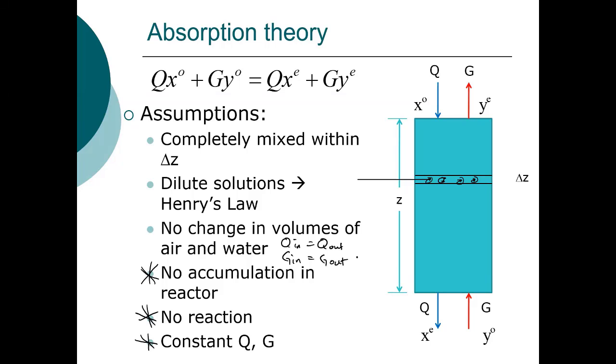Now, typically when we design these, if we're looking at removing a chemical from the gas stream, then typically the influent concentration in the water is 0. So we're looking at removal of a chemical from the gas stream.